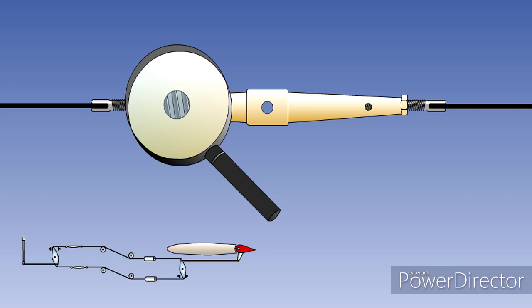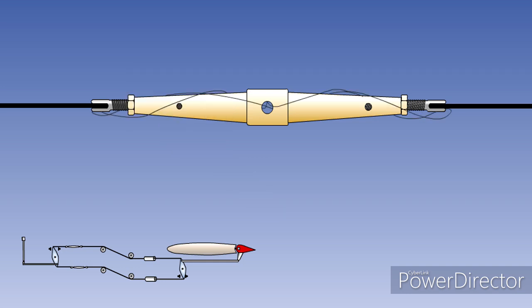To be in a safe condition, or in safety, the inspection holes must be completely blocked by the threads of the end fittings. This is verified by attempting to pass a hardened pin through the inspection hole. Once the correct tension is set, the turnbuckle is locked using locking wire or some other suitable device to prevent it vibrating loose.